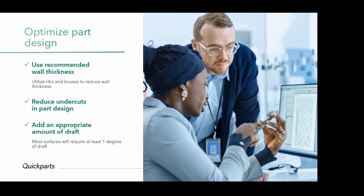Recommended wall thickness. For every material we use, there is a recommended wall thickness, right? ABS, PC, nylon, EPS, PBT, all materials have their own recommended wall thickness range. So try to keep your wall thickness within that range.